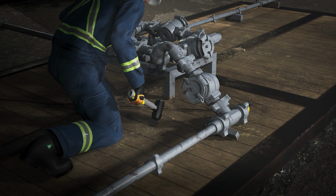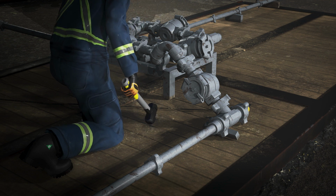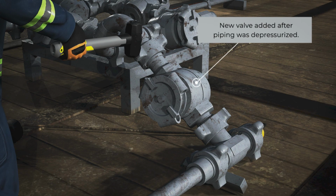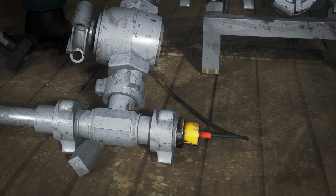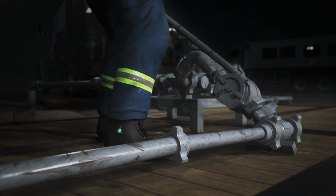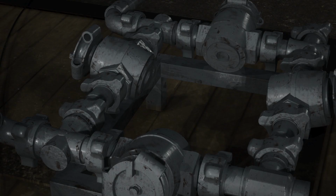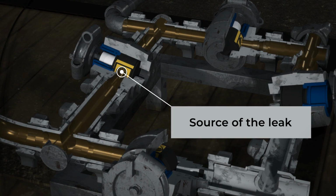Unsure of the leak's location, the crew installed an additional valve to isolate the valve manifold as a potential leak source. The additional valve was installed next to the valve manifold on the piping section going to the BOP. A pressure transducer was located between the new valve and the BOP. The crew pressured up the line to low pressure levels with the new valve open and closed it after the line had been pressurized. The pressure in the line held, which indicated a successful pressure test and identified the adjacent valve on the manifold as the source of the leak.